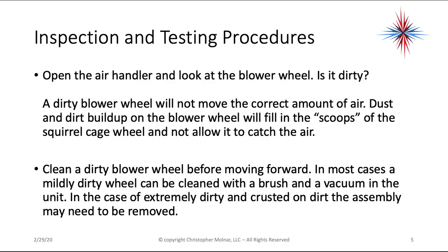Open the air handler and look at the blower wheel. Is it dirty? A dirty blower wheel will not move the correct amount of air. Dust and dirt buildup on the blower wheel will fill the scoops of the squirrel cage wheel and not allow it to catch the air. Clean a dirty blower wheel before moving forward.